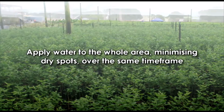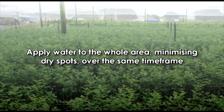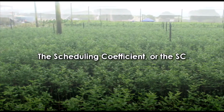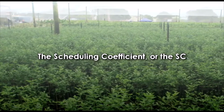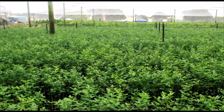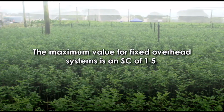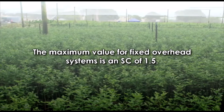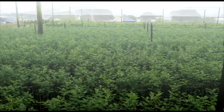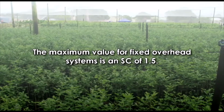Thirdly, the system should apply water to the whole area, minimising dry spots over the same time frame. Scheduling coefficient, or SC, is a measure of the extra time required to irrigate an area to ensure the driest section receives the required amount of water. The scheduling coefficient, or SC, is expressed as a number greater than 1, with 1 being the ideal. A good scheduling coefficient, or SC, is 1.2, with an upper limit of 1.5.